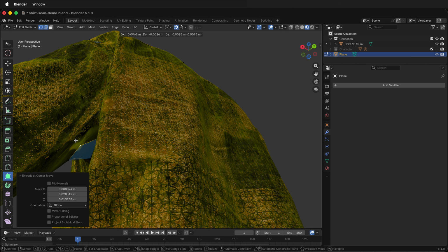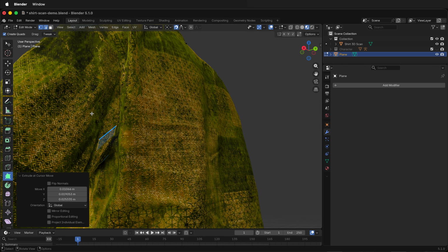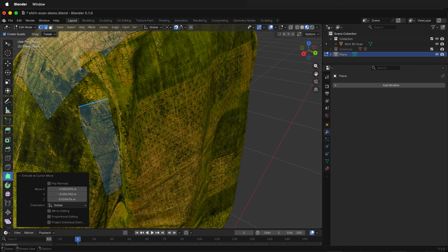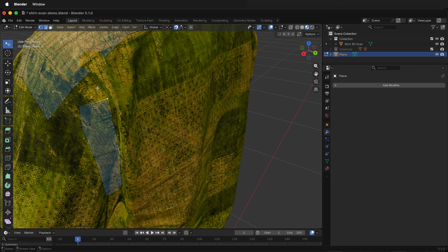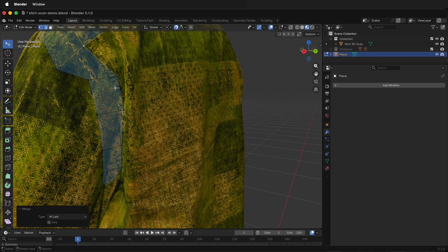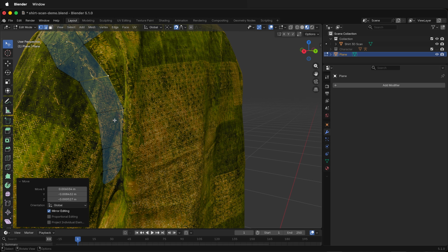You can adjust everything later. Don't be too self-conscious about how many edge loops you're creating. We can always eliminate or add as needed. Generally just kind of keep the same density as other parts of the mesh. And then I'll switch to tweak and I'll use manually merging by last, ML, ML, merge those vertices. And then I can just move these around to straighten up.